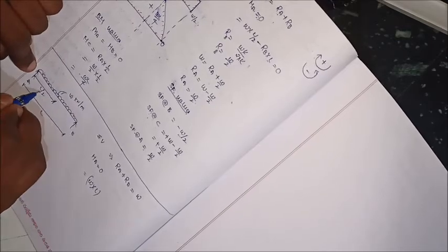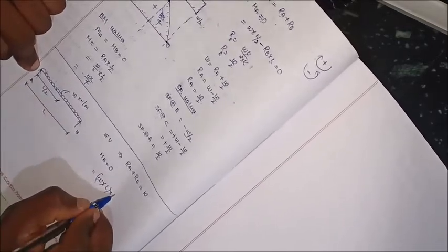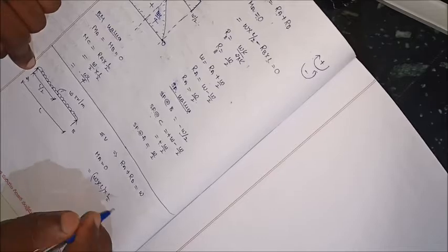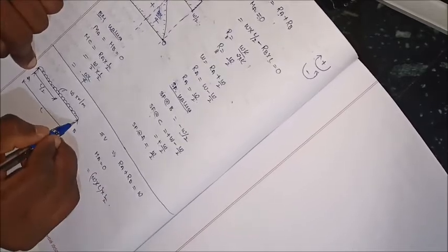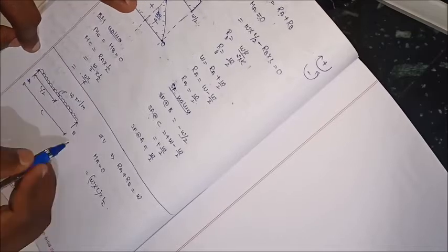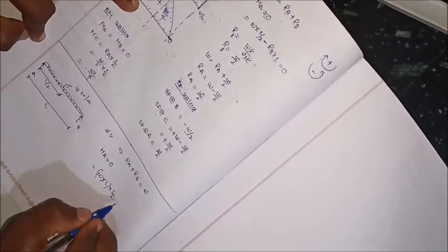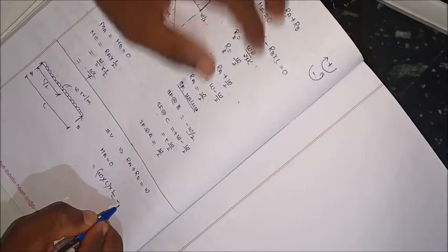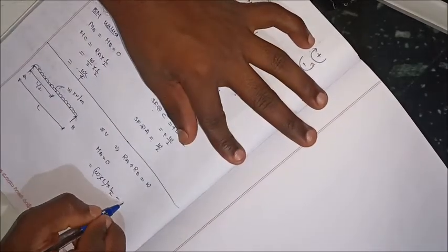From A and B, the distance is L by 2. This is the moment due to the UDL load. And then the moment due to this RB will be anticlockwise, so take negative for anticlockwise. So the moment is nothing but RB into